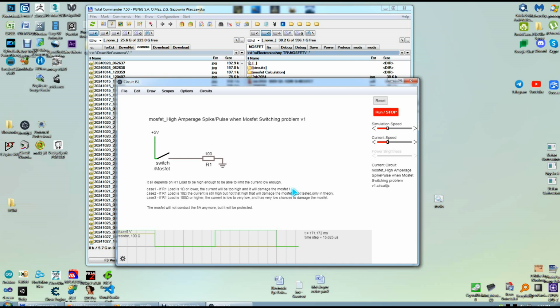So I should probably put a note here in this document, in this save file: to not damage the MOSFET, avoid that kind of switching from the power supply, do not let it switch. If you see that it is switching from voltage to amperage, then turn off your experiment. It will not destroy your MOSFET from the first switching from voltage to amperage, but if you are doing it rapidly or very fast, the switching of the gate of the MOSFET at this 1 ohm value, that power will definitely ruin the MOSFET. It will melt it inside. Okay, like I was having those issues before.